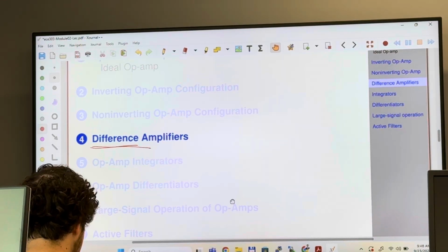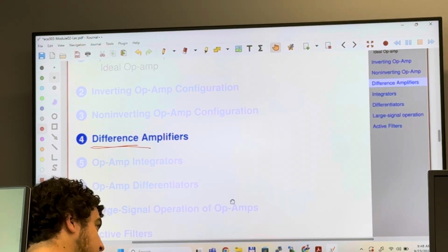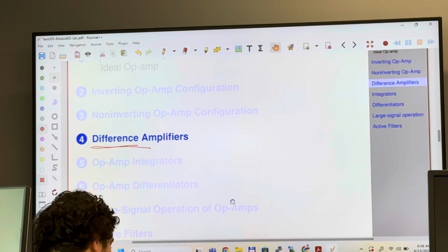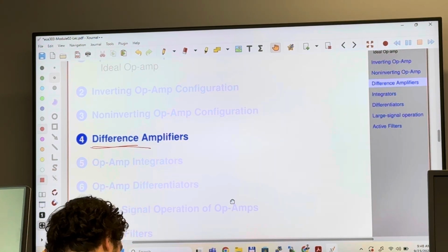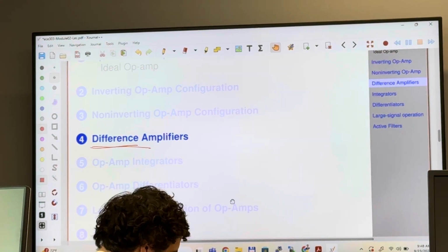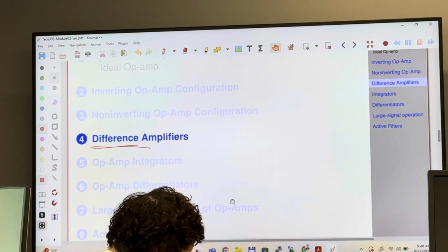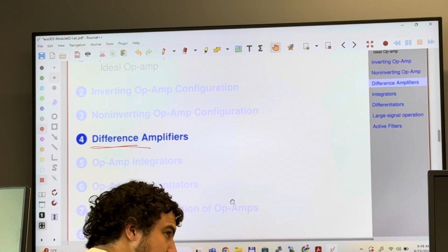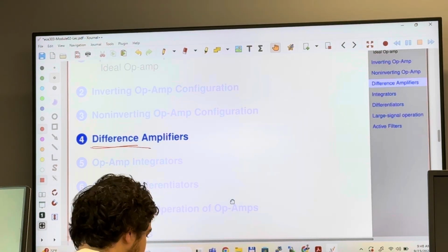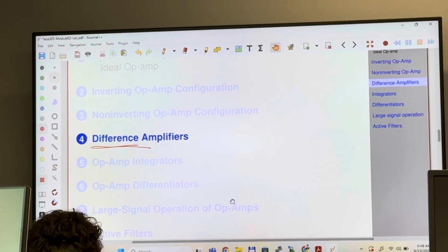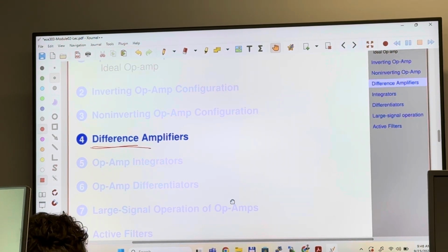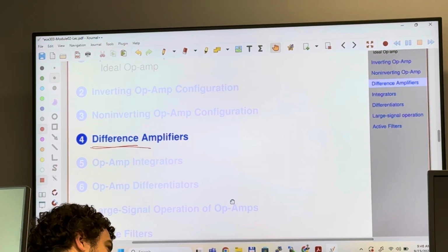These difference amplifiers, you guys work with sensors, right? A lot of sensors. Some of you are building robots, and you have sonar sensors, and sonar sensors come with an electronic board. These sensors pick up very, very small signals. Those are voltage signals, basically. When it senses distance, for example, the output voltage of that sonar is going to be proportional to the distance to the object.